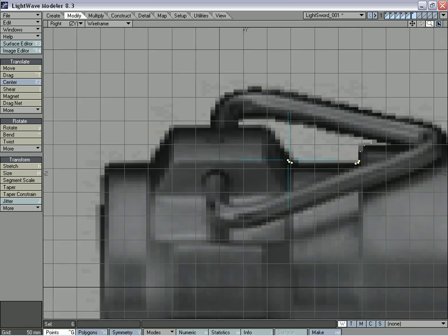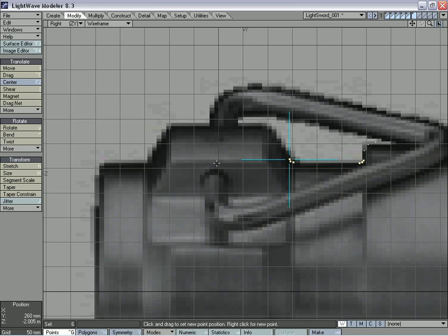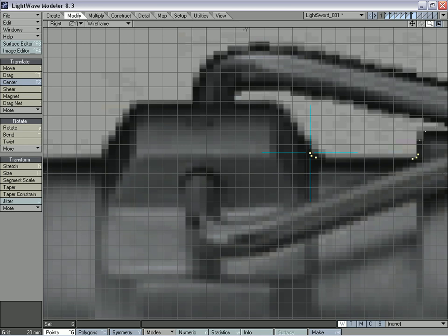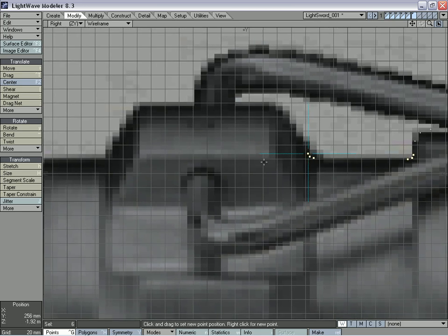And what you can do is you could create this box, just create one, and use the array tool to array it around 6 times. But what's going to happen is we're going to get a sharp crease from where this piece is connecting to the piece we're modeling right now, and it won't get that nice smooth highlighted look in there. So what we're going to have to do is model that separately after we lathe it, and there's no way to do that by lathing.